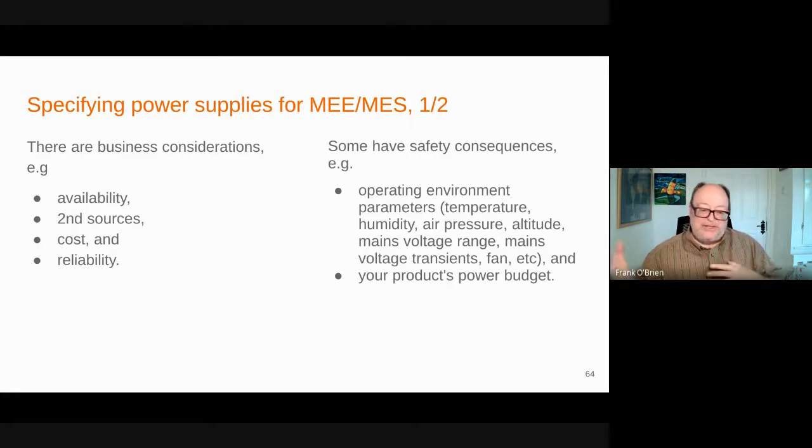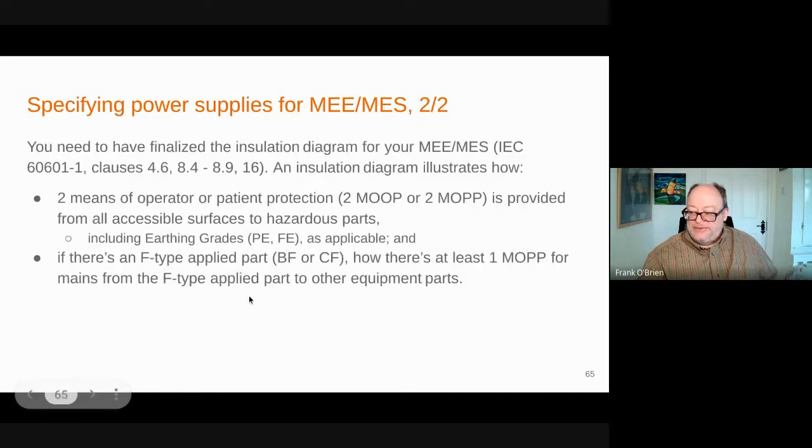When you go to buy your power supply, you need to be specifying that installation type and voltage. And then, as this says, think about your environment. You're going to operate it within the housing, so consider internal temperatures. Are you going to need a fan? Do you need to put a fuse on there, within your product? And so on, used within ratings.